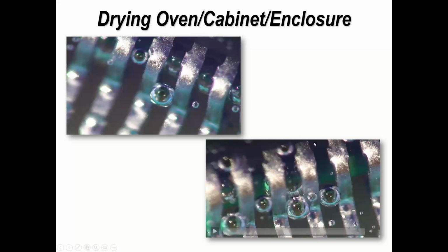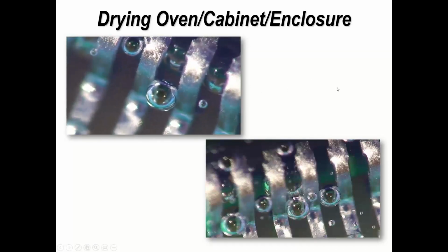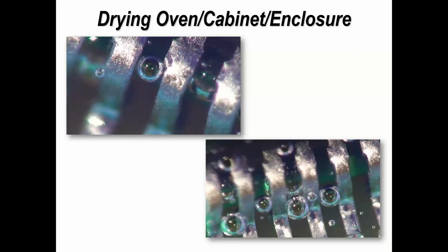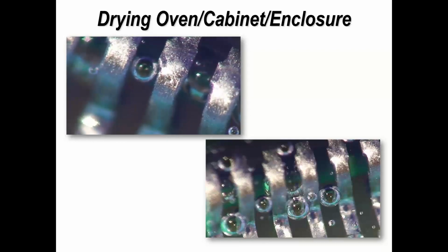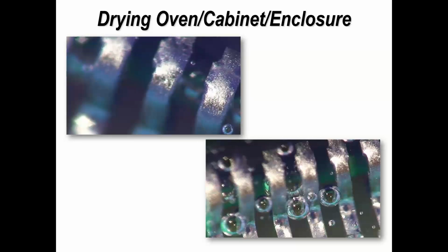Now, we've mentioned a couple of times that one of the issues with conformal coating is bubbles. And I just wanted to show you these 2 videos that I made, which just show you a board assembly and bubbles between terminations. So if you imagine you have got coating material around the leads, but a bubble there is air, so the amount of insulating material between those 2 terminations is reduced because of it. You could argue that these will not affect the long-term reliability. The problem is to try and introduce bubbles to check that is the case if you were doing testing.